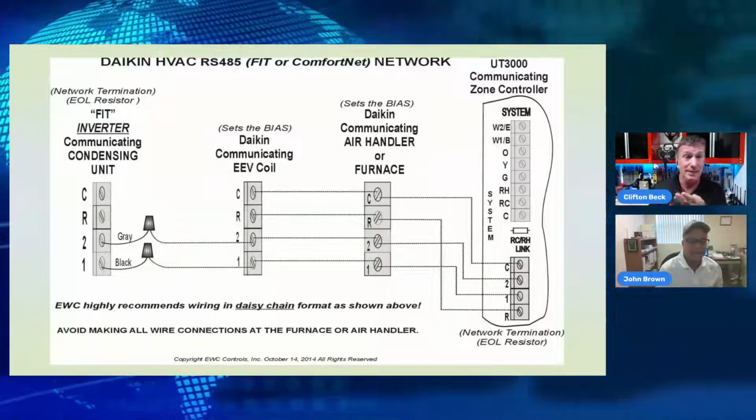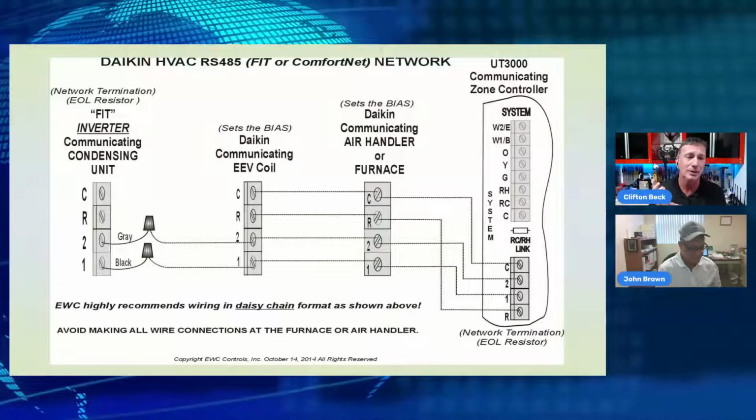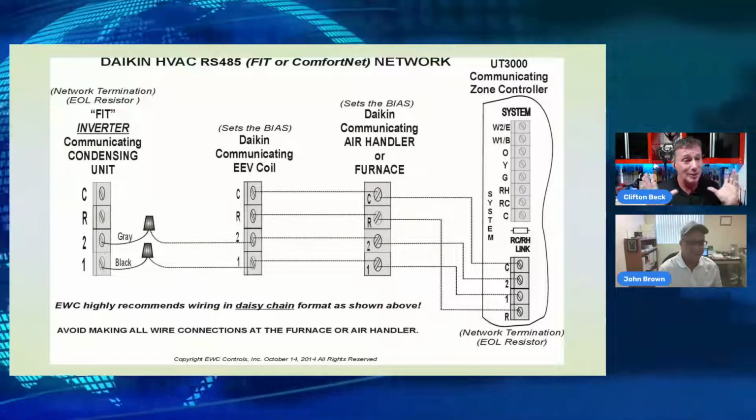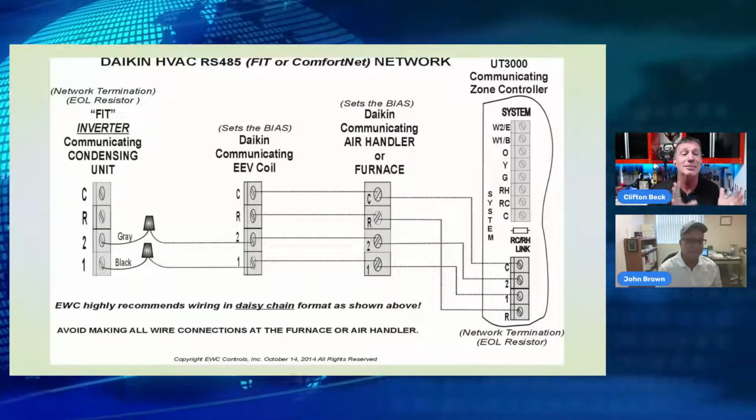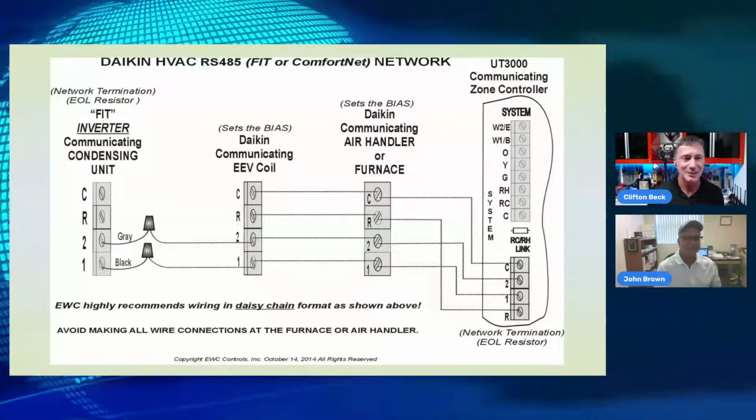Well, exactly. Doesn't it make sense just to put it at the electronic expansion valve and let the process begin at the component that does the metering? So if we know what the system is doing, if the system is functioning properly, we can read superheat without even putting a set of gauges on.